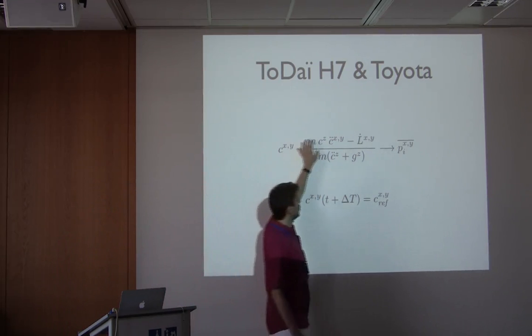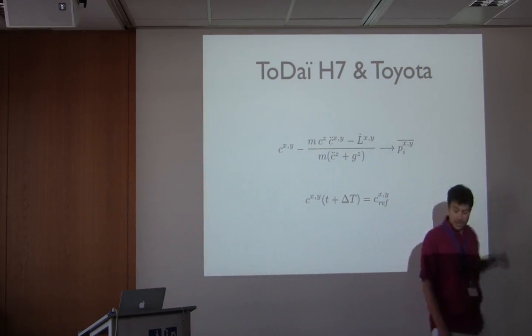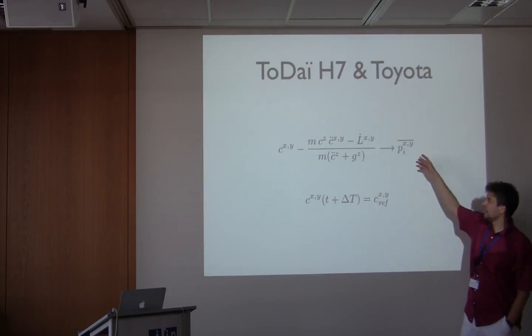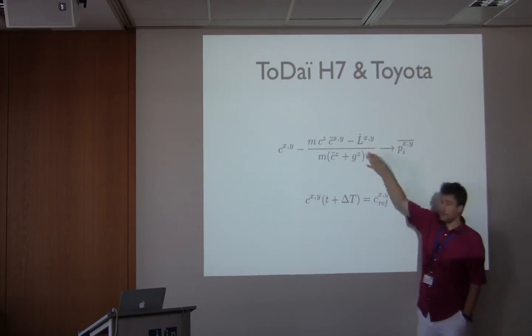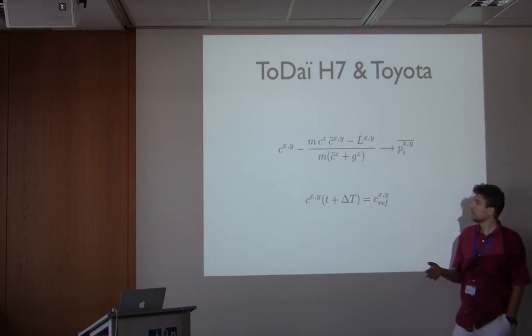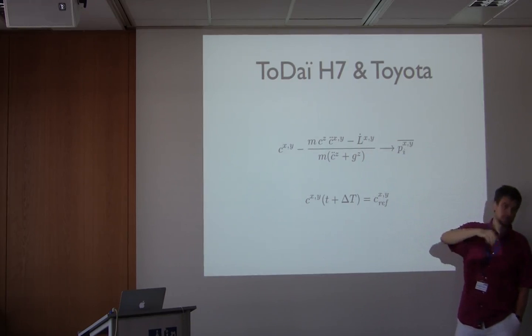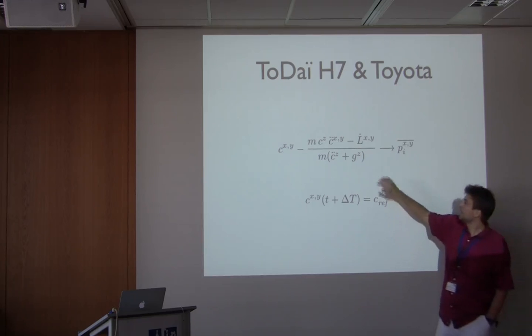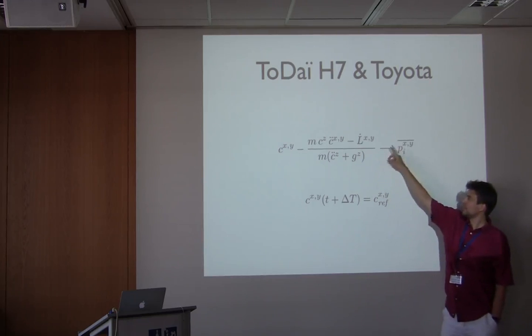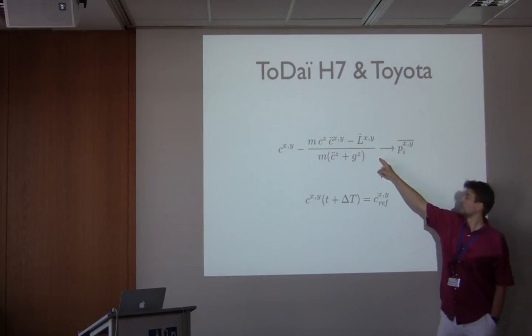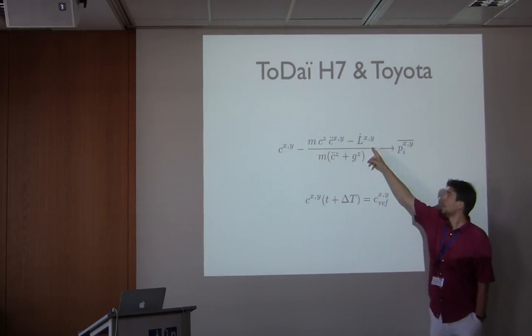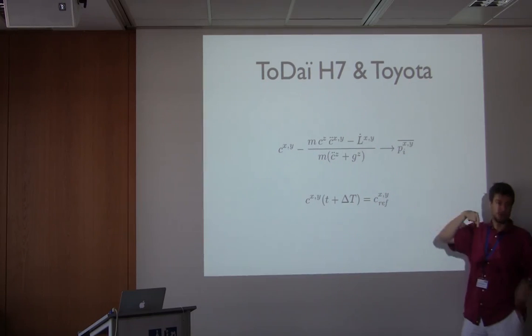You can recognize the cart dynamics. And in fact, in this cart dynamics, the angular momentum is supposed to be fixed. What is going to be adapted is the exact motion of the center of mass. It is adapted by an iterative process so that the center of pressure, because here we have the equation for the center of pressure, converges to the center of the footsteps.